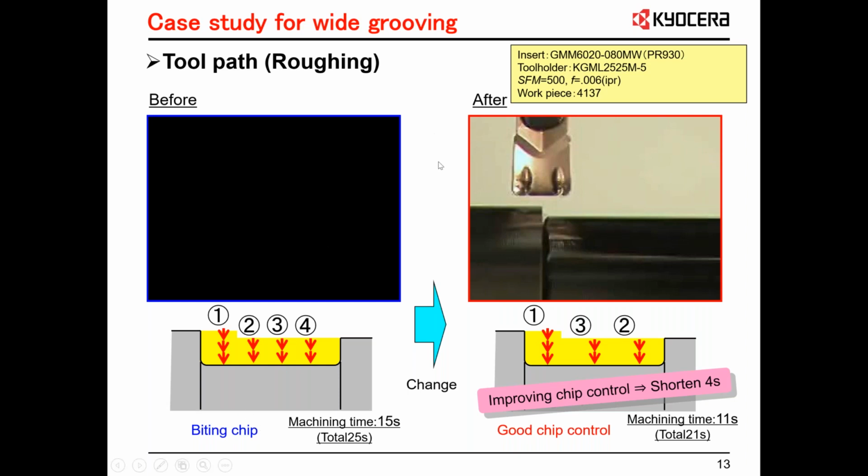We're going to alter this pass. We're going to drop the 1 pass, and we're just going to do 3 plunges this time, but we're going to alter the positioning. We're going to do the first plunge to the left, the second plunge to the right, and then the third plunge in the middle.